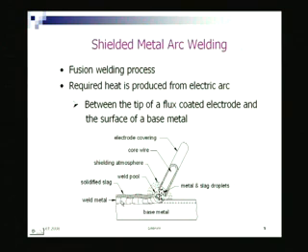Thereby, you have the weld metal deposit over which you have a solidified slag. That slag is nothing but the burnt flux, the coating that it has over the electrode. That burnt flux is termed slag, and under that heat the slag remains in a molten state, which floats over the weld metal and thereby provides shielding to the molten metal, right.